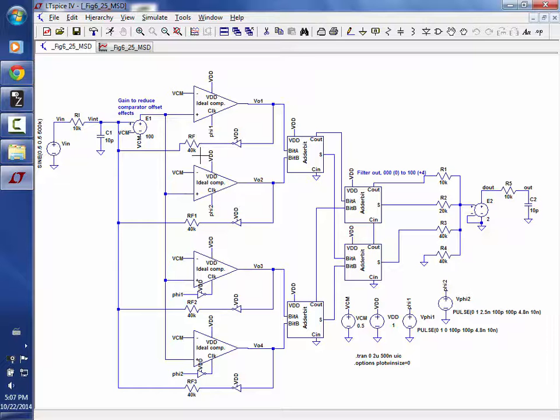Any questions? Okay, so let's look at a couple more and then we'll quit. I just want to plant this in your head. The forward path doesn't have to be precise. We can make mistakes. I get the high-speed sampling by putting it in the feedback path. Using multiple paths allows me to increase my sampling frequency. I'm not going to get real high resolutions, but if I have a digital bit stream in here and I'm trying to detect it, I might be able to get, with a 4-bit or 6-bit A to D converter, all of it digital. And once it's digital, then life is good because then I can use DSP to extract, where are the edges?